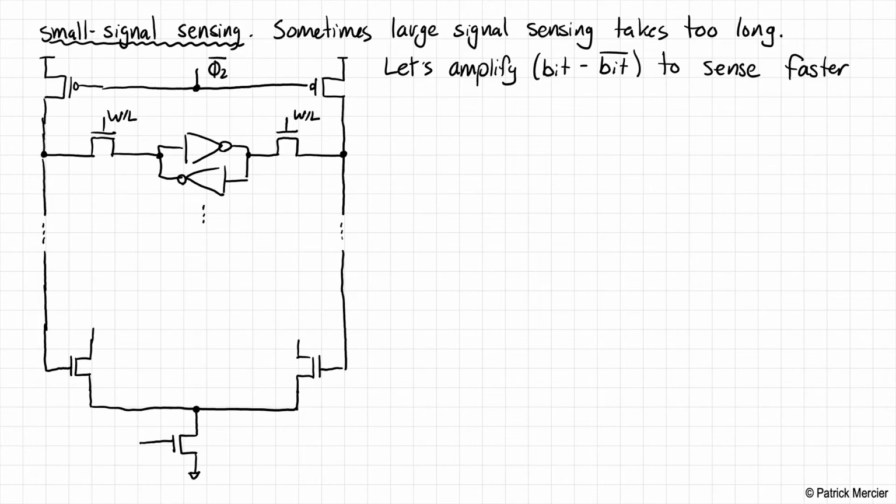So normally what we do here is we will then have either a resistive load or a load based out of transistors that effectively act as resistors in our differential amplifier. In this case, I want to do something a little different. In fact, I'm going to load this circuit with a cross-coupled inverter pair. So I'm going to basically put an active circuit in my load. This is a very strange idea, at least at first. So we have our inverter here as follows.